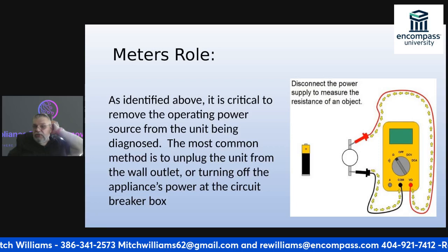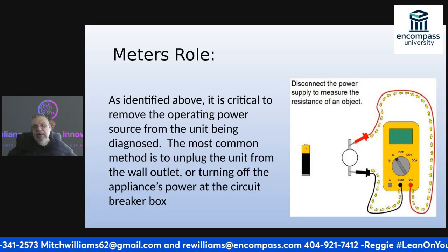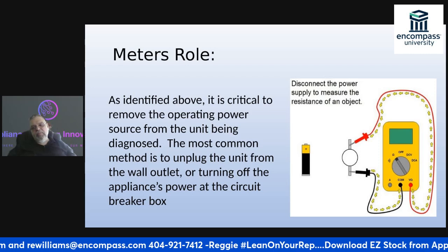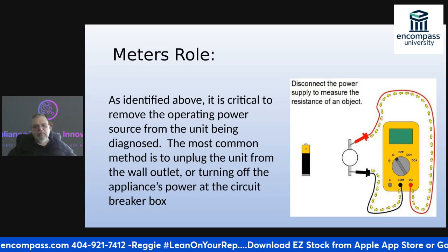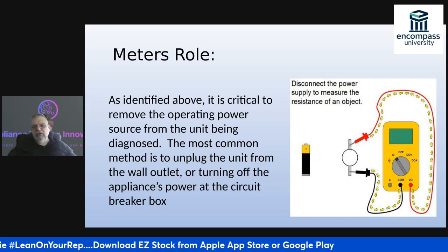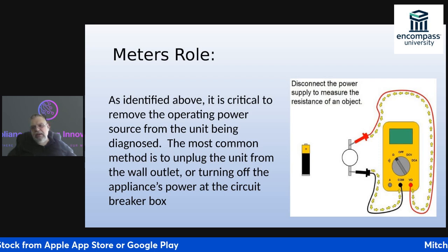As you see, this one right here has a battery. It does not have a fuse. You'll blow this meter up if you have it plugged in. If you look at this, it shows the path for the common. It flows through the meter and it goes out to the other side.